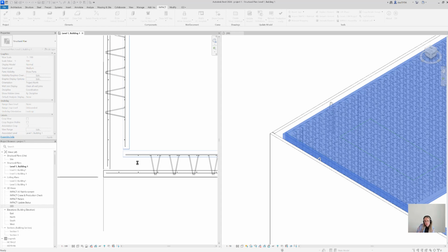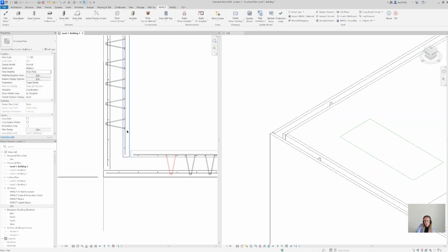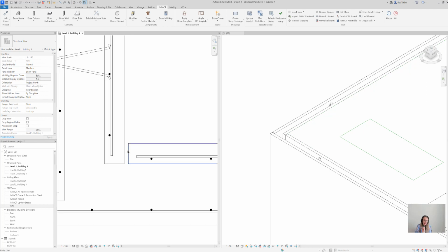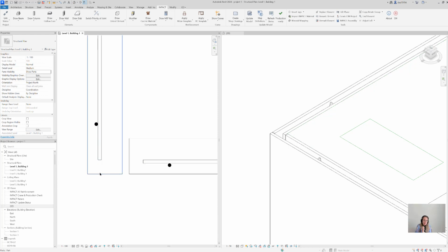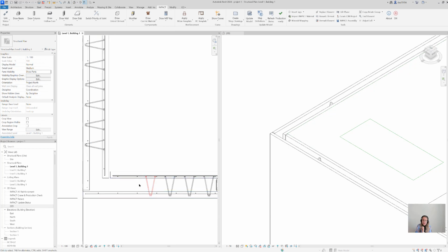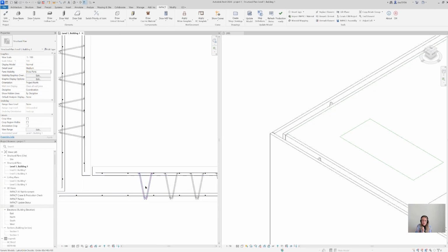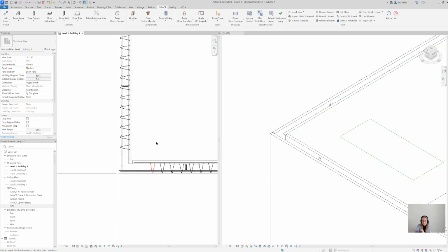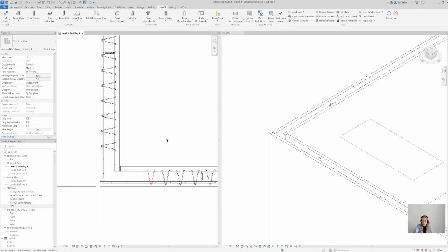Impact is taking the other panel, the vertical, and it goes by this one. And what happened is that's not only a minor change in the geometry, but also Impact is adjusting the reinforcement for you. So if you have mesh or reinforcement and you predefine some cover, it will be adjusted by Impact. And the lattice girder will also be adjusted. Now this one is red, right? We're going to explain why this is happening in a while.